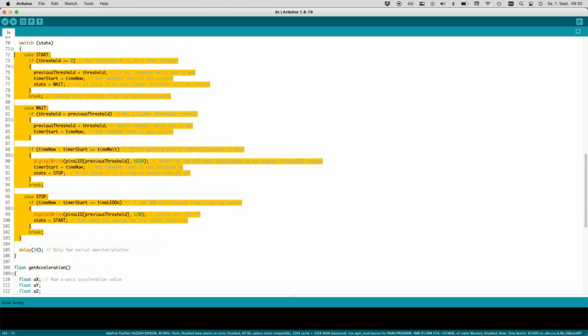Now we use a series of switch case statements, a principle known as state machine, to make sure that the right thing happens at the right time in a controlled way. This is how it works. Depending on the 3 state variables you declared in the enum, only the code of a certain case block will be executed. The break statement directs code execution to the end of switch case, in other words, back to loop.